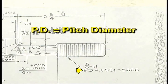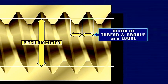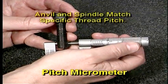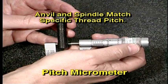One of the most important features to measure on a threaded feature is the pitch diameter, since it affects both the ability to assemble and the strength of the assembly. Pitch diameter is the diameter of a threaded feature measured between 2 lines which intersect where the widths of the thread and groove are equal. Special measuring instruments are used to measure pitch diameter, such as a pitch mic. The mic will have a specific anvil and spindle to match the thread to be measured.